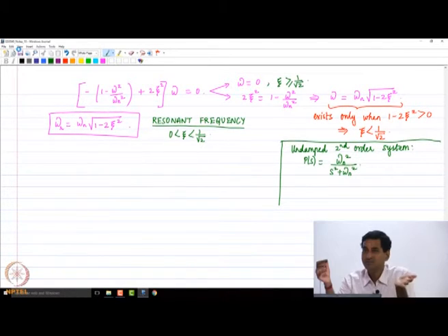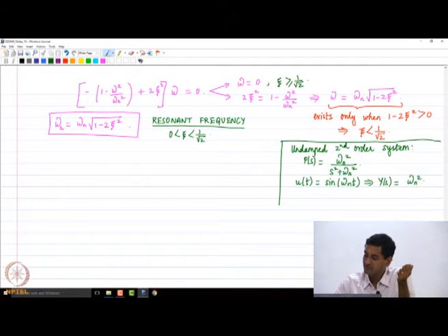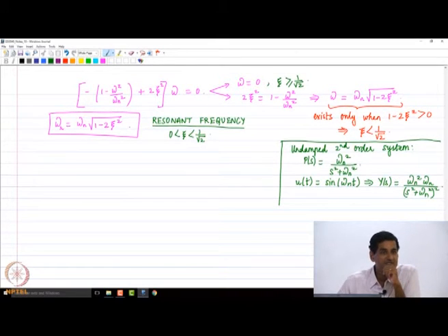So, that is how we have the visualization of natural frequency. You give a perturbation, and the frequency at which the output will oscillate is essentially the natural frequency. But if you also give an input which is, let us say, sine omega n t, what is going to happen to the output? We are going to get omega n squared times omega n divided by s squared plus omega n squared whole square, right. So, once I have this, what will happen?